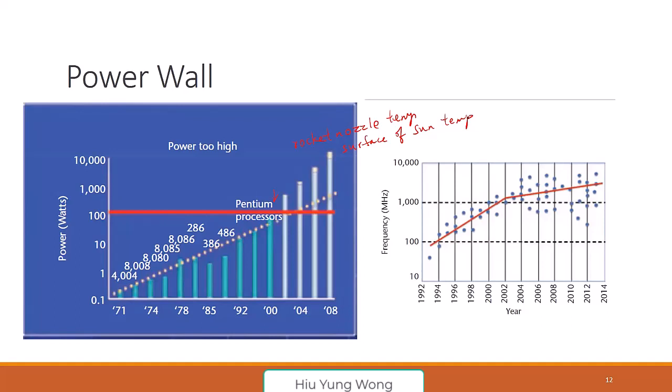So see what happened. Intel, at this inflection point, which is called the inflection point in the paper, slowed down the frequency. So what is power consumption, right? It's the frequency times CV squared. C is the total capacitance of your chip, V is the voltage swing, and frequency is how fast you operate. If you don't operate, yeah, no power consumption. If frequency has to slow down, we cannot keep going. Then that's a big deal. Then your transistor, your CPU, is not improving.